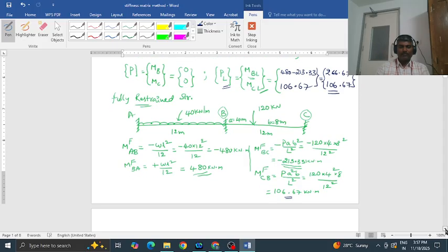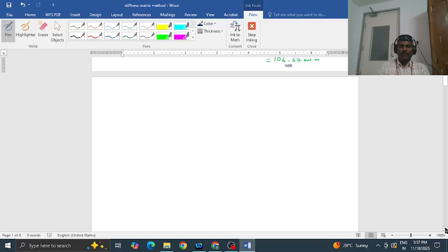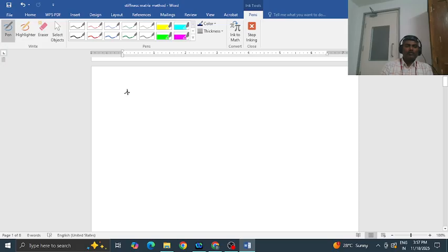Okay, right. So once you are done with the P and PL matrix, now it is time to develop stiffness matrix and then further inverse of it. So as the Ki value is 2, we'll have 2 by 2 matrix. So now we are going to work out these values utilizing the symmetry. We are going to work out only these three values because K21 will be equal to K12. So how you do that? Kij, Kij. Okay, see that?